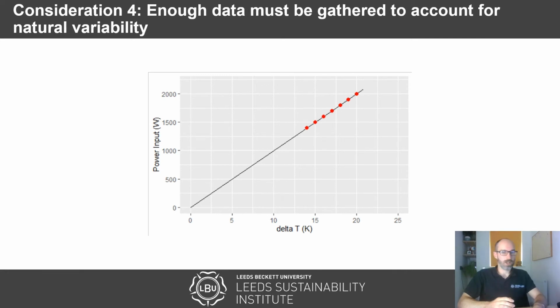The next consideration to think about is that you do have to run your coheating test for a sufficient number of days. So far I've showed you coheating plots like this where the points lie perfectly on a straight line, but of course this will never be the case. You will have some variability on the points, in part due to the imperfect solar correction and party wall corrections that get applied, but also due to other variability. So wind can cause variability, and rain, etc. There's many things that can cause the points to lie away from the true HTC line.